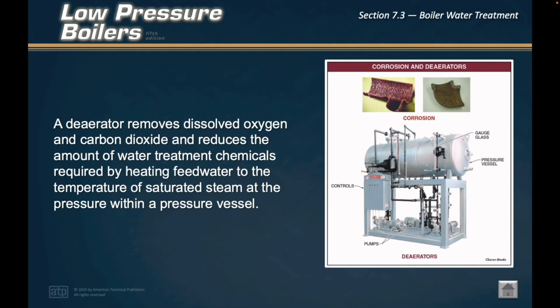Dissolved oxygen and carbon dioxide can be removed with chemicals. Depending on the system, it may not be practical to chemically remove the dissolved oxygen and carbon dioxide from the feed water. In these cases, a deaerator should be installed.